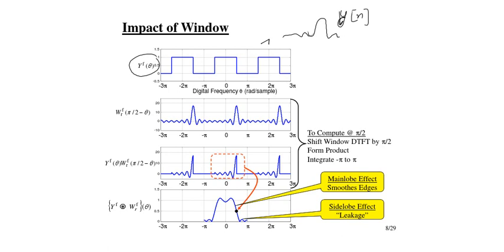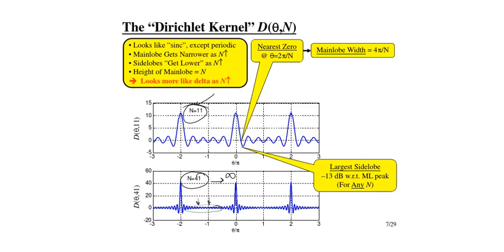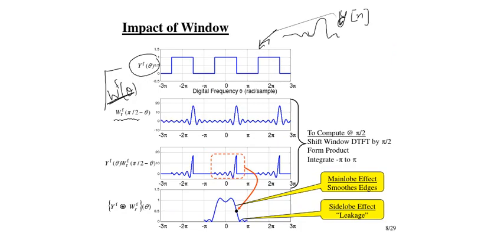So when we write this down, we have to find the circular convolution of this and W of theta, right? This is also the DTFT of the window that we have already covered in the last slide. When we find the circular convolution with this, we have to shift the second signal for circular convolution. So we shift it for different lambda, where lambda goes from minus pi to plus pi, because the DTFT is periodic between minus pi to plus pi, or 0 to 2 pi.